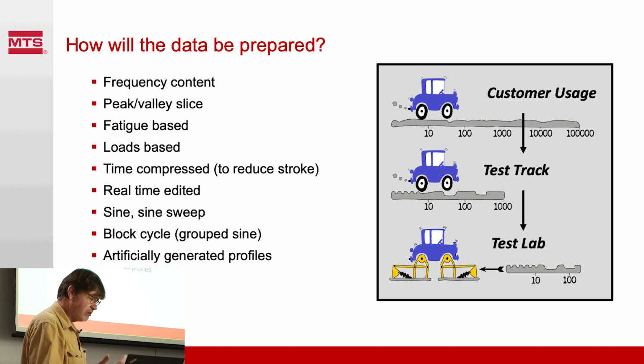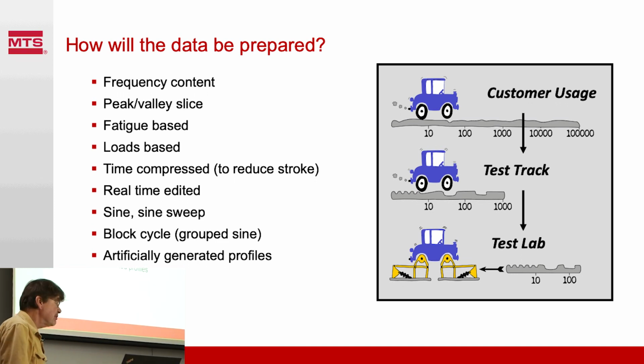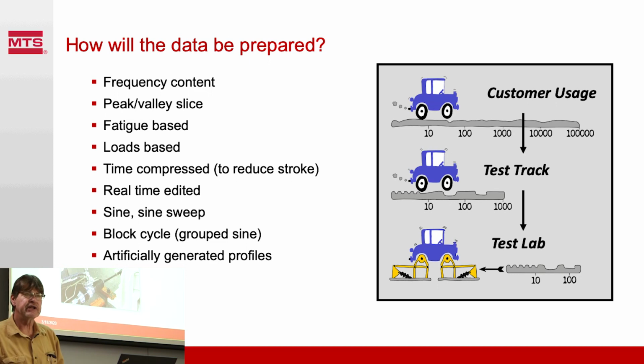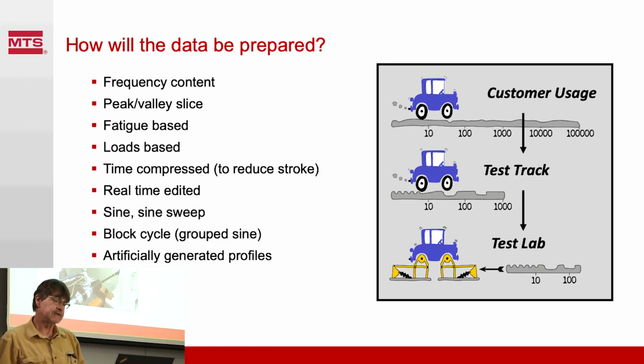We can do sine sweeps, block cycles. In today's computer world, we can generate a lot of artificial profiles. We can combine those and figure out how we're going to use that data to control our test.